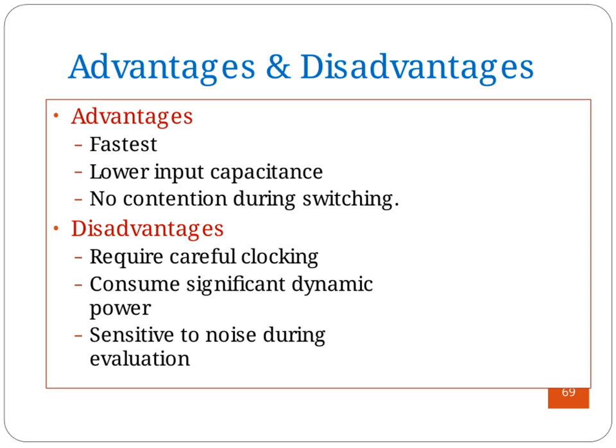However, there are some downsides to consider. First, it requires careful clocking to ensure everything operates correctly, which can add complexity to the system design. It also consumes a significant amount of dynamic power, meaning it could be less energy efficient in certain applications. Lastly, this design is sensitive to noise during evaluation, so it's important to maintain a clean and stable environment to avoid errors. Overall, while it offers speed and efficiency, these trade-offs must be managed carefully.